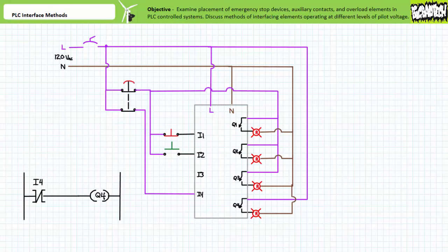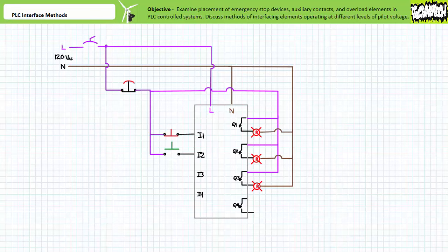It should be stated that the placement of the E-stop is system and application specific and must take into account the needs of the process and those conditions that operators must be protected against. In summary, a properly placed E-stop should disable a system as quickly and reliably as possible with minimal, if any, reliance upon the PLC. In the interest of keeping things simple, let's just assume for this and the remaining applications that the E-stop is a hardwired bottleneck that disables all incoming and outgoing communications to and from the PLC.